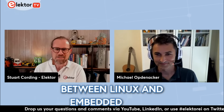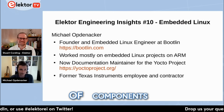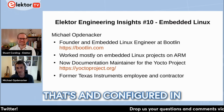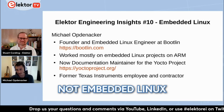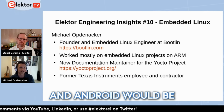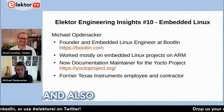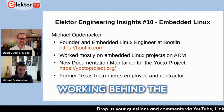So I think the first question, maybe to clarify, just to really set a baseline for everything: what is the difference between Linux and embedded Linux? I'd say it's still Linux, but with a reduced set of components, configured in a custom way. So using this definition, Raspberry Pi OS is not embedded Linux because it's a standard desktop kind of OS, and Android would be, which is a bit weird. Also, embedded Linux is Linux when you don't recognize it, when it's hidden on a system, working behind the scenes.